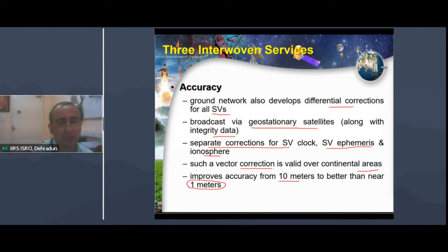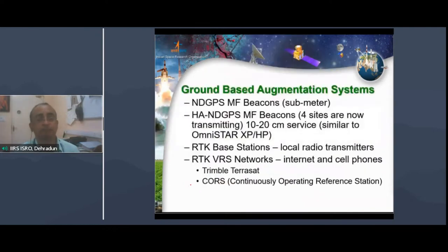So without doing anything else, we can just keep the SBAS facility on in a GPS receiver, and then if we receive the coordinates, the accuracy in the data will be just 1 to 2 meters. But we have to check that my GPS receiver has the SBAS facility.